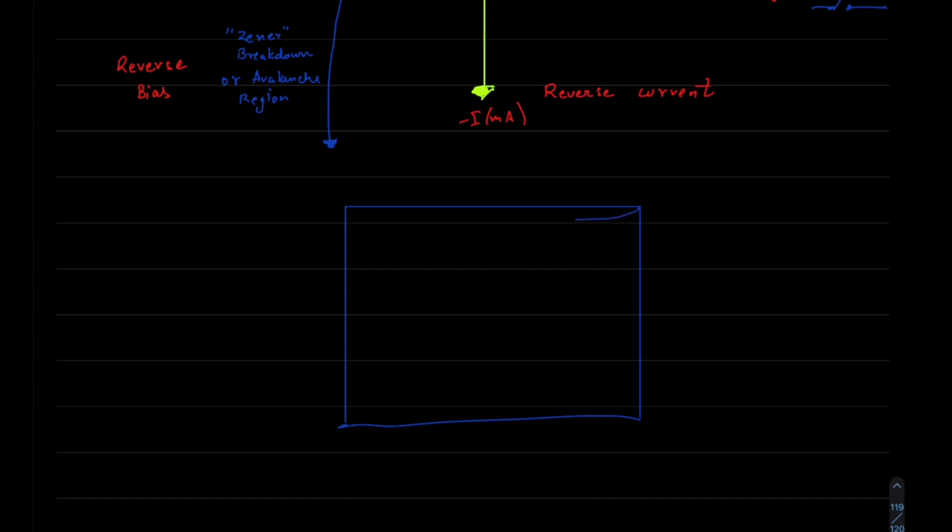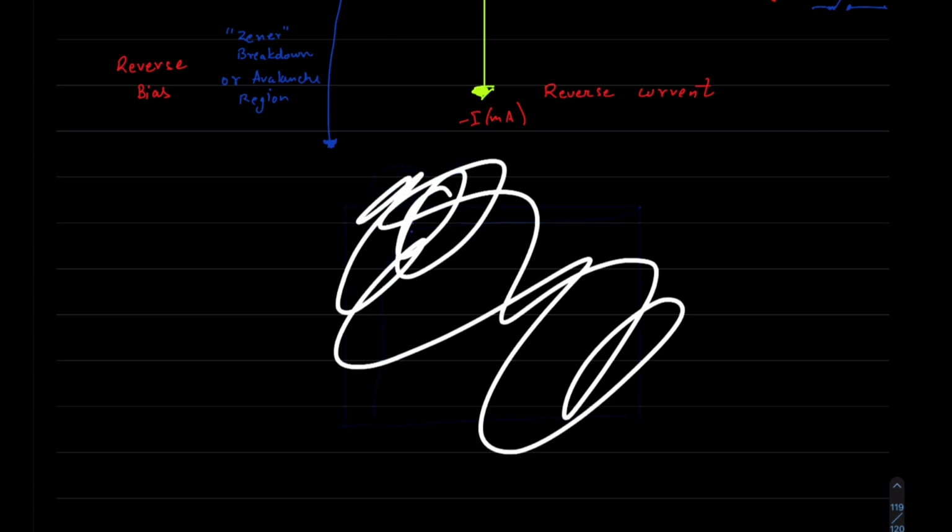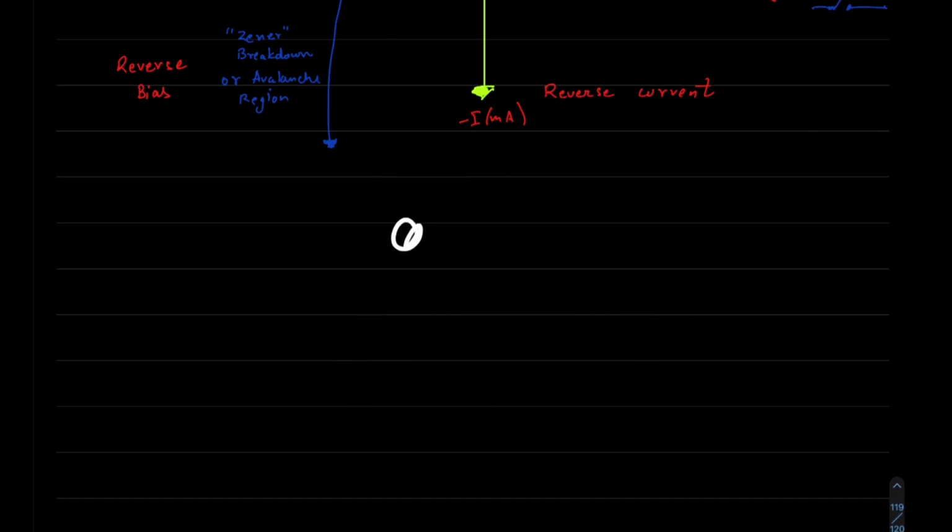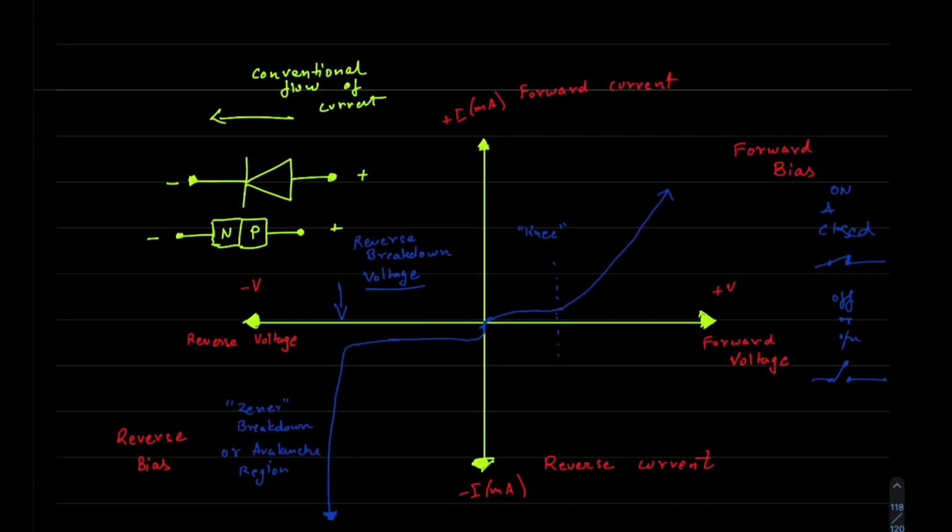And it goes like here, and we have the breakdown voltage, and it starts going down rapidly. That's also called the avalanche reverse breakdown phenomena. So we know there is a small amount of current flowing through it called the leakage current.